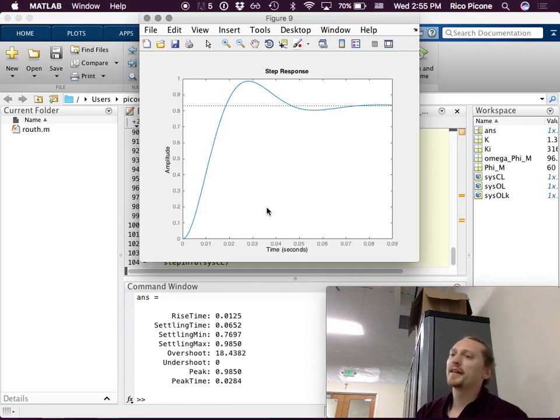When you get to this point, going back and choosing a different phase margin is just more work, because you know this is a monotonic function and the gain is going to decrease if you go one way and increase if you go the other way. So instead of picking out a phase margin to iterate on, you might as well pick out a gain to iterate on, because they're essentially equivalent in this case. So yeah, I would just probably adjust the gain around until you got the overshoot that you wanted.